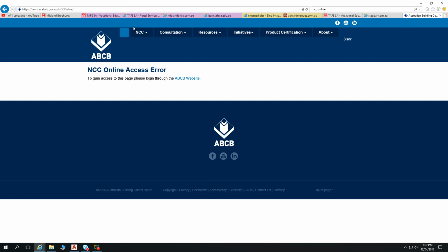Yes, for the roof level. But if it's a flooring system that you change, it ends up being a very thick floor, as a designer, I'd pinch all that from the lower floor, because down the lower floor we've got car park and we've got storeroom. We don't really need 3 metres head height for a car park. And I'd be pinching it from that and leaving the ceiling heights in our apartments alone.